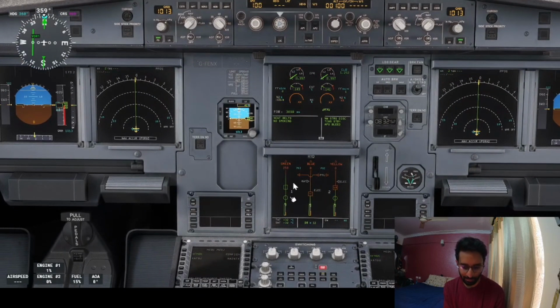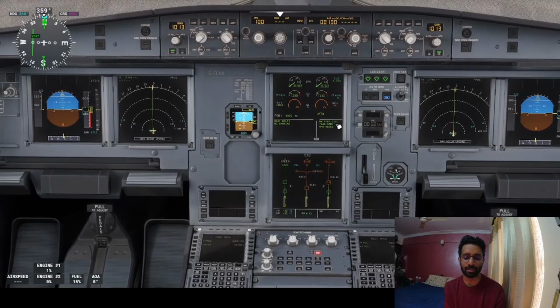See what happens? The EDP immediately kicks in and the green pump is pressurized. Why is the PTU not running right now? Yes, 500 psi is there. Parking brakes, so both masters are off? No. Here one master is on, so that condition is gone. Both masters are on? No. One master is off, so that second condition is not met.